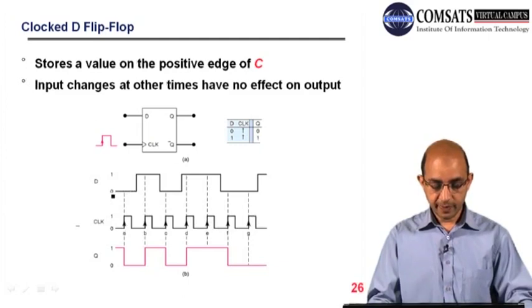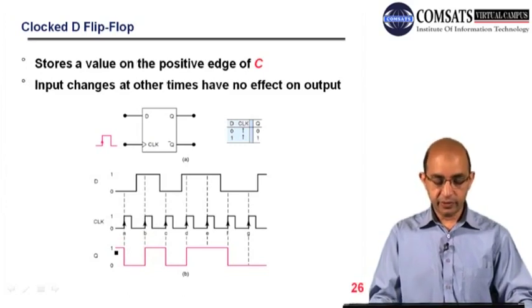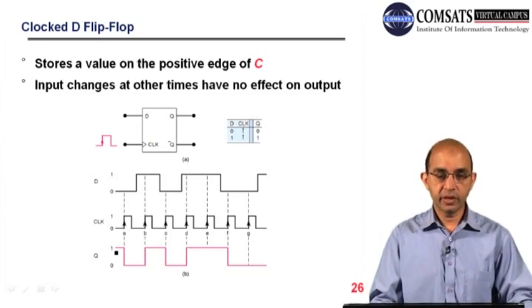And this is the input, D. It is normally better if we place dashed lines regarding the active clock edge, so that we can draw Q. So here you can see we have Q. Q is 1 when we started, because you can say that 1 is already stored there.